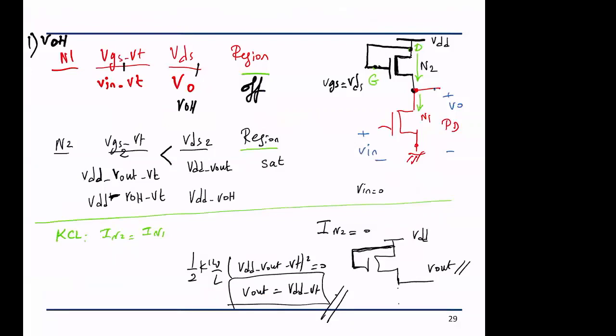inverter. And we said now I will have an NMOS to act as the pull-up, as the connection between VDD and the out, and another NMOS to act as the regular pull-down to which the input signal is arriving. And we said that in order to solve for VOH, I set Vin for the main NMOS to be less than Vt. Okay, so this is my device.